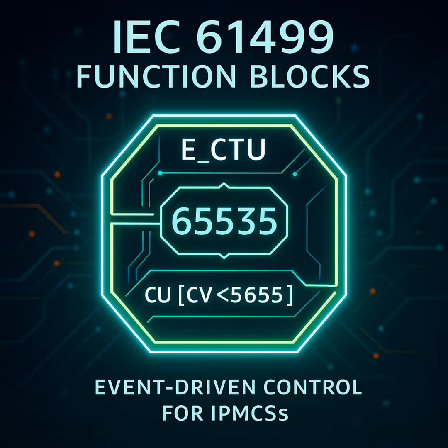Okay, let's take the simple one first. The R event, the reset, what does the ECC do? When the R event comes in, the ECC triggers the internal R algorithm. And the standard is super specific about what that algorithm does, right? Absolutely precise. The R algorithm is defined as CV := 0, Q := FALSE. CV gets 0, Q gets false. Two assignments happen conceptually together. It wipes the slate clean, sets the count to 0, clears the done flag.